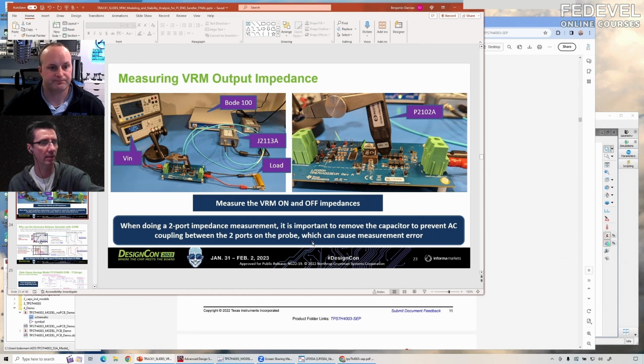So we measure impedance for every frequency, and then how do we use these results? Yeah, so we're measuring close to DC, and I think in what I showed in the plots, around 10 hertz is where I start, and we go out to 50 megahertz, which is the limit of the instrument. And how do we put these results into our model?